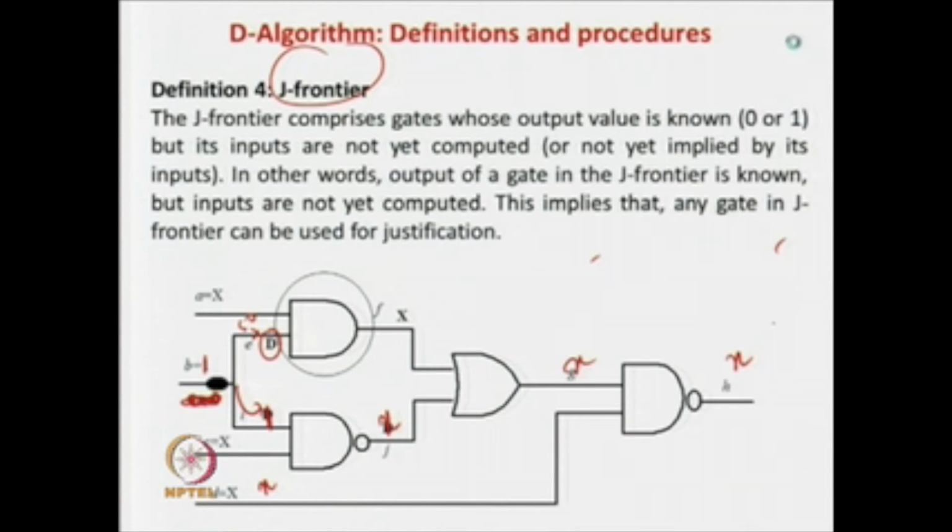So, for some of the values, by the sensitization process or some other mechanism, what happens is that once you set the value for some reason, like in this case you have set the value of 1, then automatically this is stuck at 0, and this net does not have any fault. Because we know that in case of a fan-out circuit, this net and these nets are actually independent of each other. So if net I is independent of net E, then this value can be directly incorporated from here. Now why can it be incorporated?